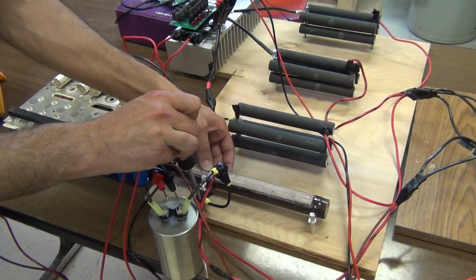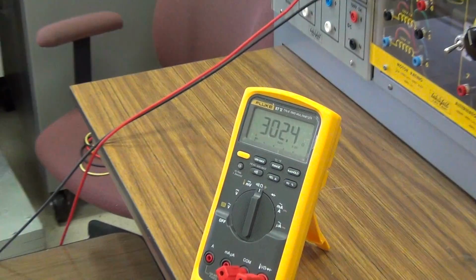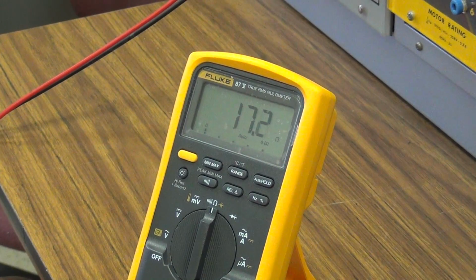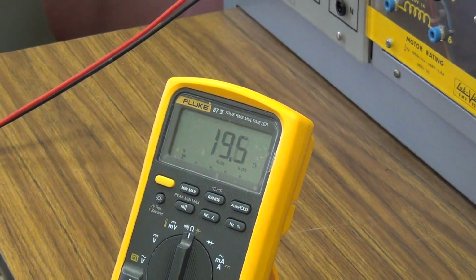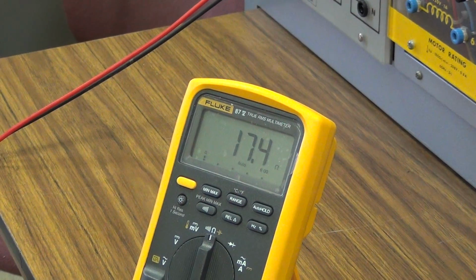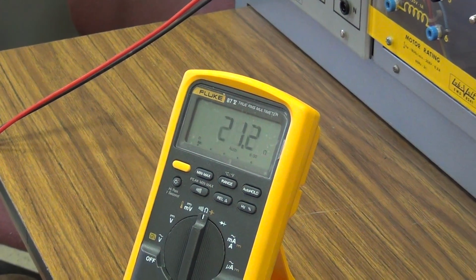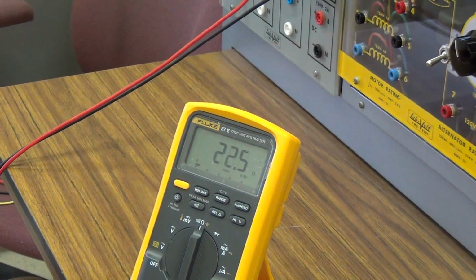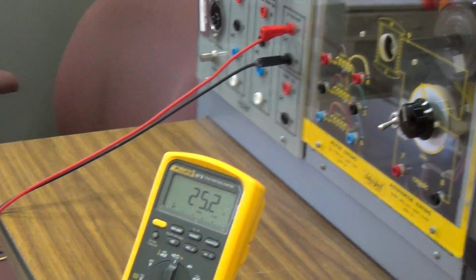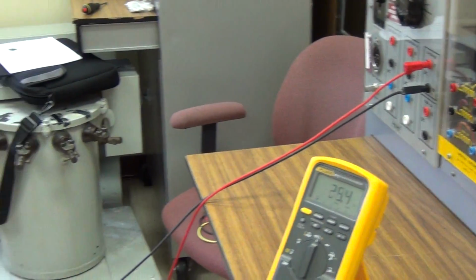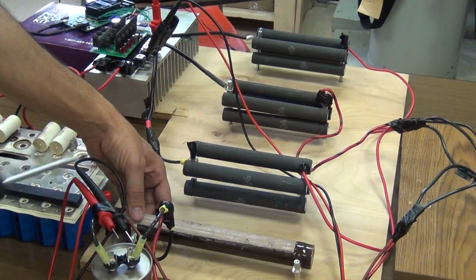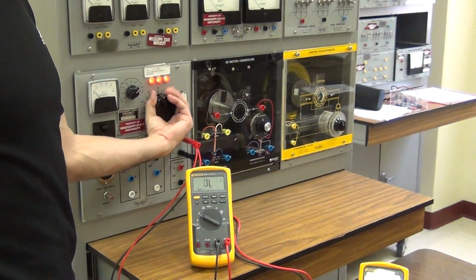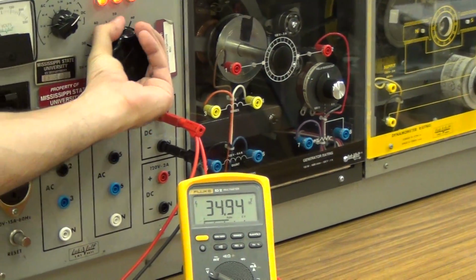For example, let's go to something like 20 ohm. This is 20 ohm. You know, the resistance is in parallel with the capacitance. So when we have a high resistance, the load is almost capacitive, and this is not recommended because we don't have a filter, and the voltage spikes will be higher, so the harmonic interaction from the DC side to the AC side will be higher. Now again, we need to increase the voltage to something around 70 volts.